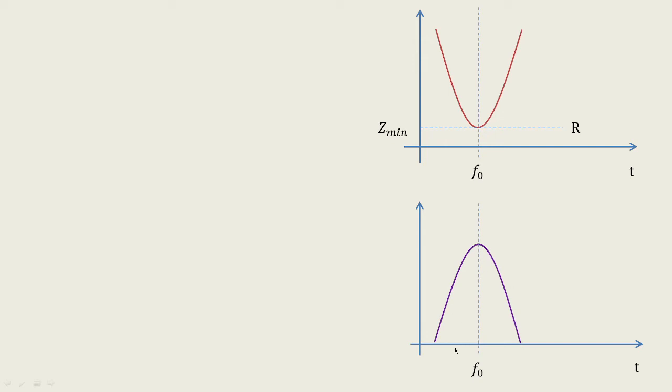In many texts or literatures, you can see this is how we get the curve for current, because the current is inversely proportional to the impedance according to Ohm's law. So this is how we get the graph for current as well as impedance under resonance. The maximum value could be V by R, where R is the value of minimum impedance. So this could be the maximum value of current, which you are going to get at the resonant frequency.